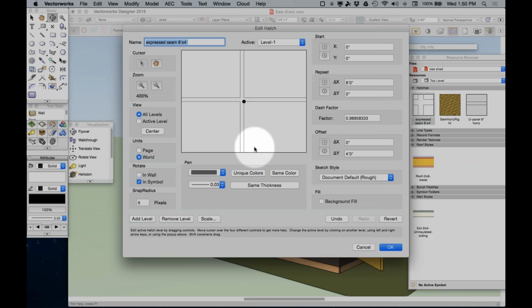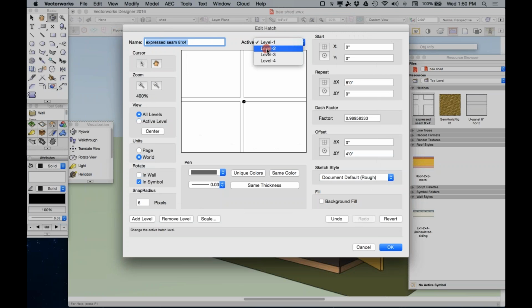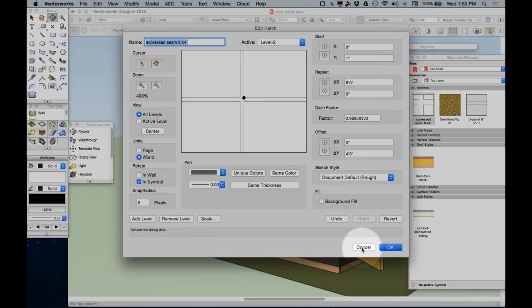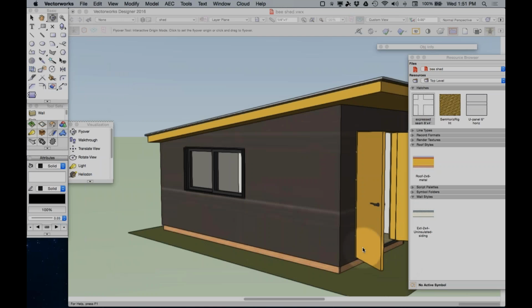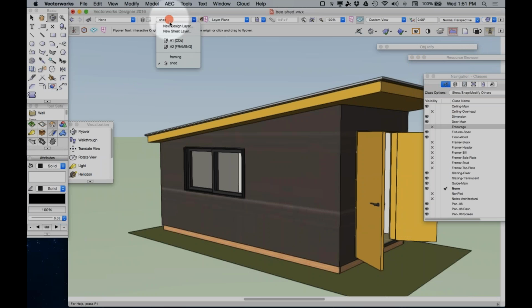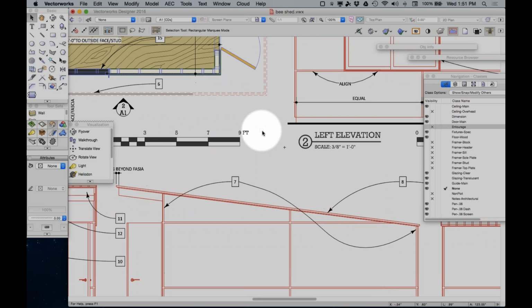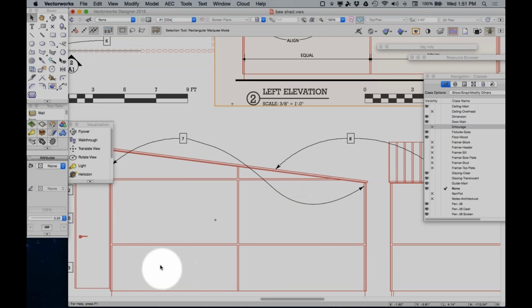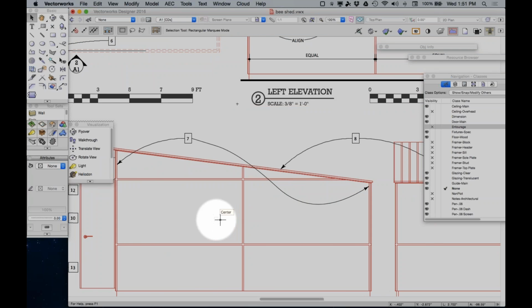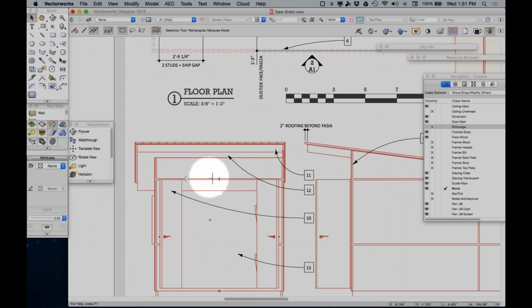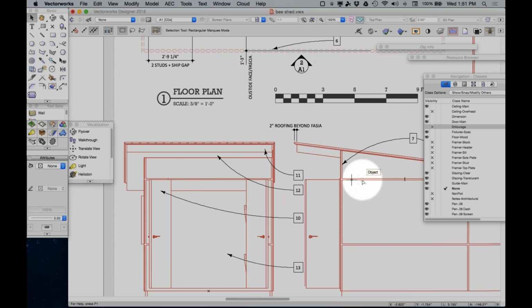And so I've got these different lines which compose this hatch, and there's a ton of hatches out there in the wild that I can import and edit, or I can create my own. And then when it gets time to show those elevations, if I want a 2D elevation, then I can just align the hatch to the appropriate place in the wall and get the seams to line up, say, with the top of the door, for example. Right? So you can see how that seam there is lining up with the top of the door.